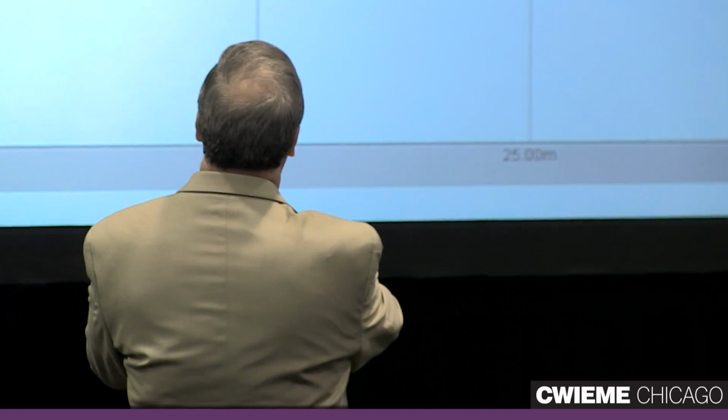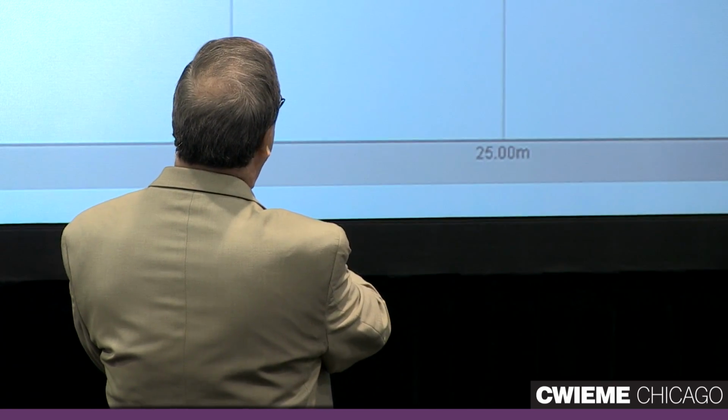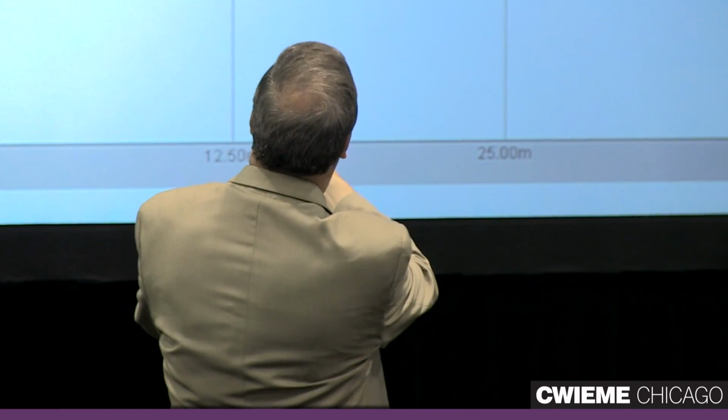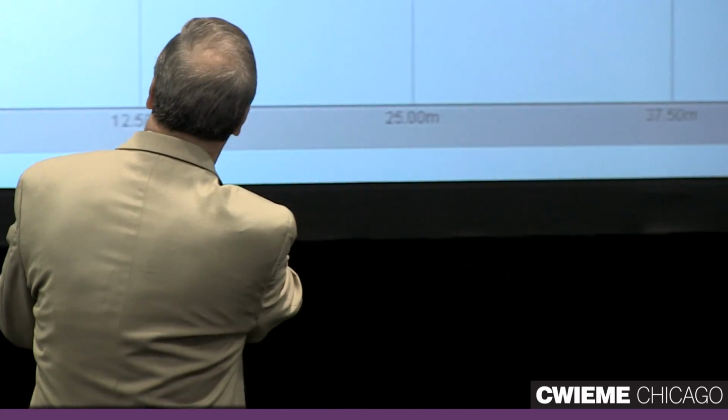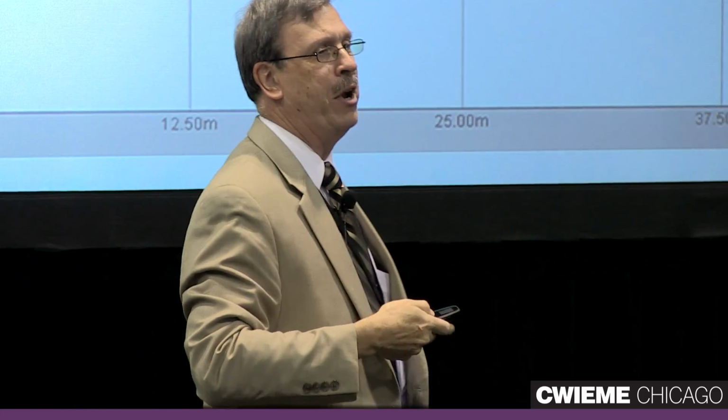Let's take a look at another one. Here's a 7th harmonic. How do I know it's a 7th harmonic? Let's count them. Starting right here, we got 1, 2, 3, 4, 5, 6, 7. So sure enough, it's a 7th harmonic. We can measure the amplitude. It's almost 11 amps RMS. And the phase angle is about 282 degrees. So it's a little bit past the peak negative point, and that's where it's at right here. It's starting to come up towards 0 there.